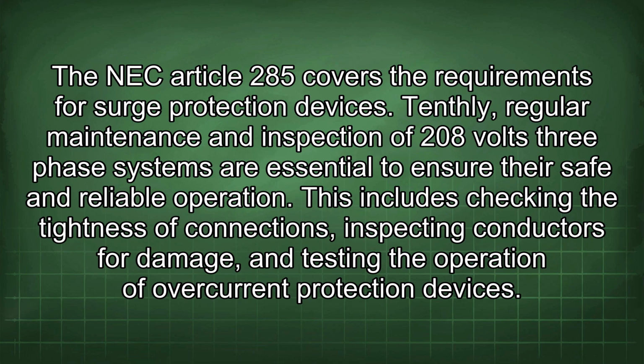Tenthly, regular maintenance and inspection of 208 volts three-phase systems are essential to ensure their safe and reliable operation. This includes checking the tightness of connections, inspecting conductors for damage, and testing the operation of overcurrent protection devices.